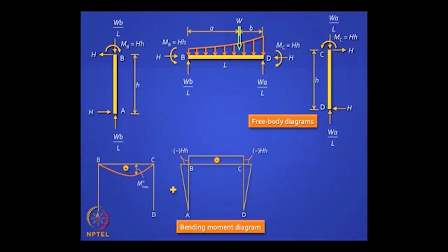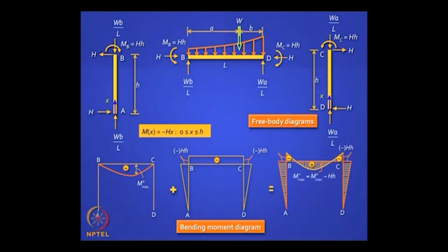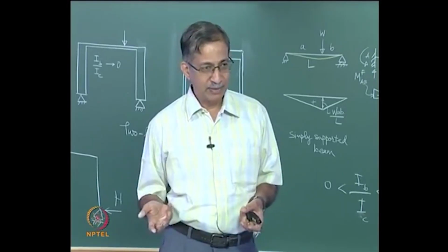It is a linearly varying bending moment, right. So this is your resultant bending moment diagram. Can we write this expression for the column? That is, if you take the column and say starting from the base x pointing upward, is this expression correct? Whether you write plus or minus depends on your convention, but let us say we are sitting inside that frame, so it is kind of outside, so we can treat it as hogging, right.